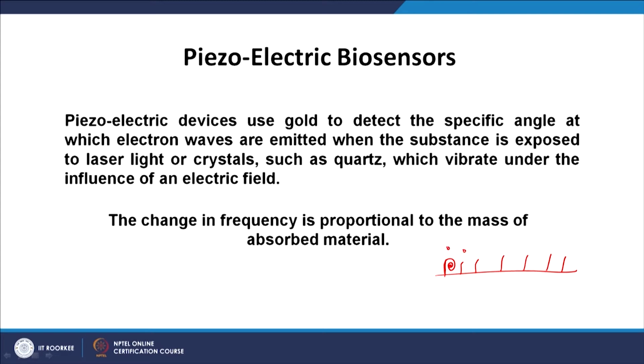Other objects that are not targets will just pass away and will not attach to the piezoelectric material, but if you have the analyte then it will add to the mass. When the mass changes the frequency changes, and by noticing the change in frequency of this piezoelectrical material you can get an idea of how many analytes were detected, so you have detected and quantified your analyte. This is how piezoelectrical biosensors work.